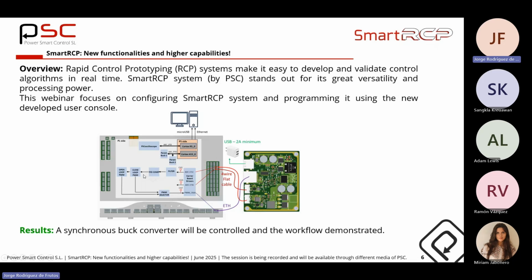In here, we have the reception of the analog input signal. We have a filter stage, then a PID compensator, and then we have two options. We have a generator of PWM pulses, which is connected to the PID compensator, and another one that generates open loop pulses.